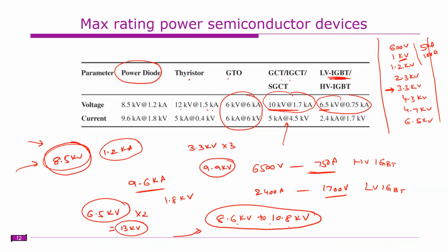That means you need to connect three IGBTs in series to form a single switch, and the gate pulse for all the IGBTs is the same.